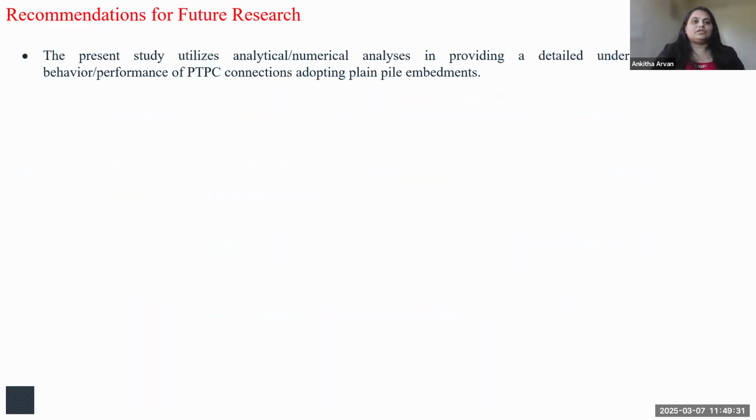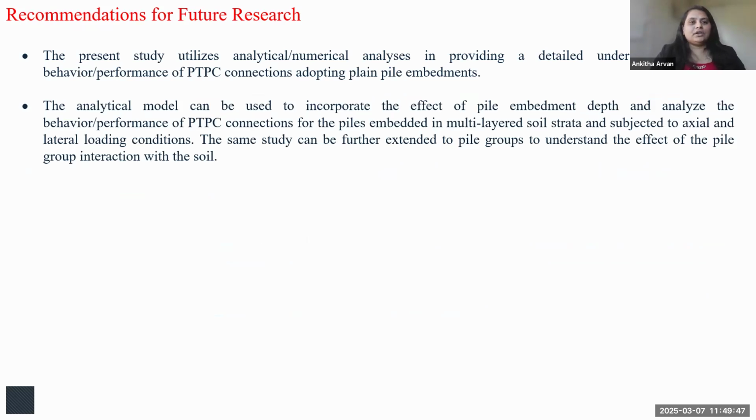So for future work, the present study is just utilizing the analytical and numerical approaches and providing a detailed understanding of the behavior of PTPC, adopting plain pile embedments. Of course, this study could be extended to understand if a reinforcement at that point affects the level of fixity or anything as such. Then the analytical model can also be used to incorporate the effect of pile embedment depth and the analysis of behavior of PTPC connections for piles embedded in multi-layered soil strata and subjected to axial and lateral loading conditions. And this could also be further extended to pile groups to understand the group interaction with the soil, because right now we are only dealing with a single pile.